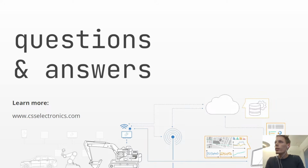Let me see if there are some other examples here. So here is another example where they are asking which device is best suitable to decode electric vehicle CAN bus data in order to get information like state of health. And I get this a lot. There is not a specific device that is better or worse for recording electric vehicle data. You can do this with any of our CANedge devices and pretty much with most CAN loggers on the market. The key is just that you're able to get access to the raw CAN bus data.